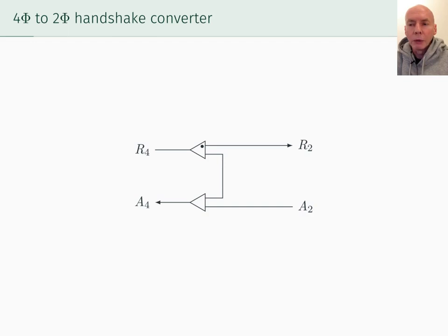One way of defining it would be if you put both circuits in black boxes and you can change the inputs any way you want, could you observe any differences on the outputs? And if you could, then they're not equivalent, but if you can't, then they are. And if you define equivalence that way, then obviously these circuits aren't equivalent, because if you raise the input A2 on this circuit, the change comes straight out on A4, whereas on the other version, if you raise A2, it goes no further than the join, and nothing ever happens on the output. So you could tell them apart that way.